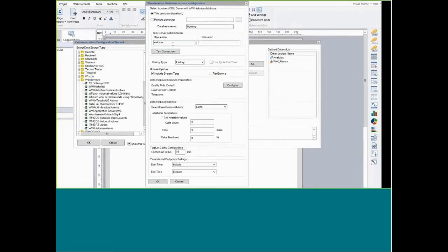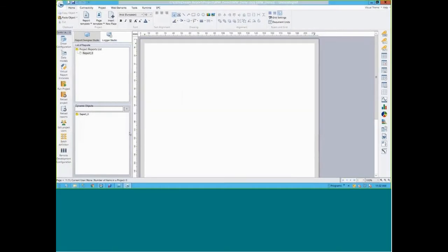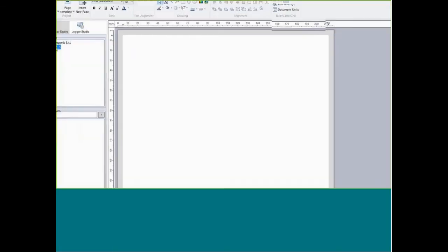First of all, we're going to use our authentication to make sure we securely log into our Historian database, test our connection to our database, and then select the retrieval method we're going to use. Of course, Dream Report supports all the retrieval methods of our Historian. We are going to choose the Delta retrieval, which gives us the most granular retrieval.